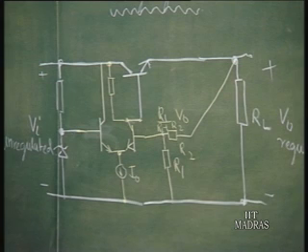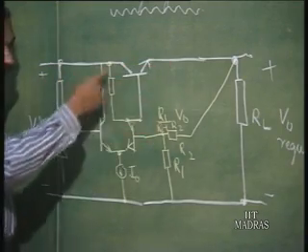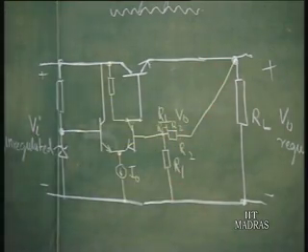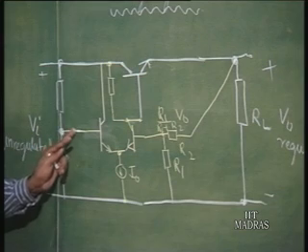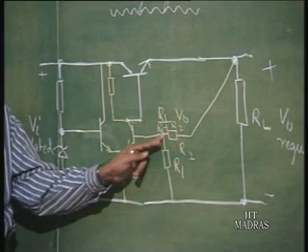This structure we had earlier indicated as the basic structure, which will involve a voltage reference, a series pass transistor, and a comparator, okay, and the load. So, actually the comparator is comparing the voltage reference with a portion of the output voltage.